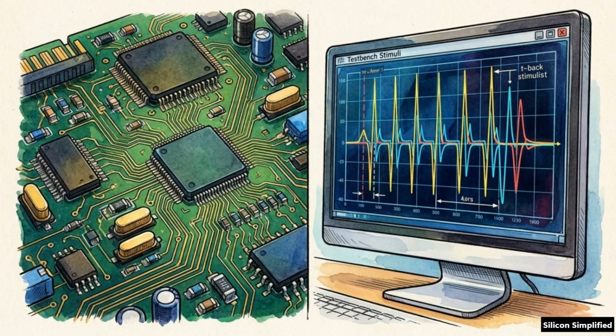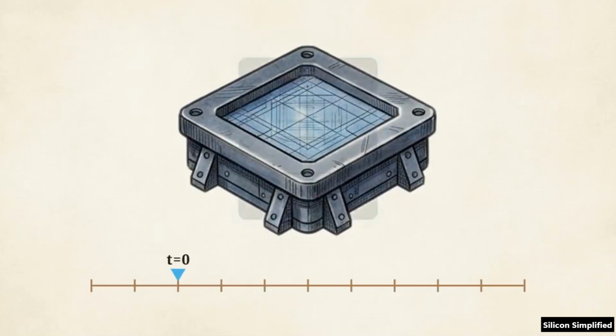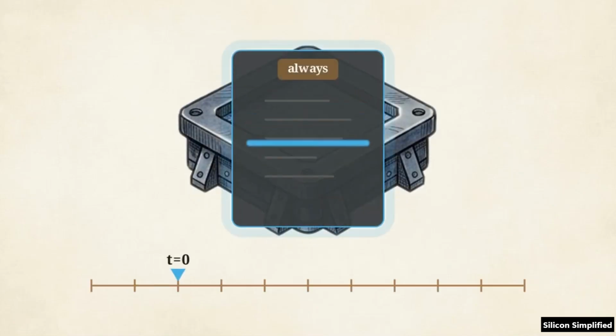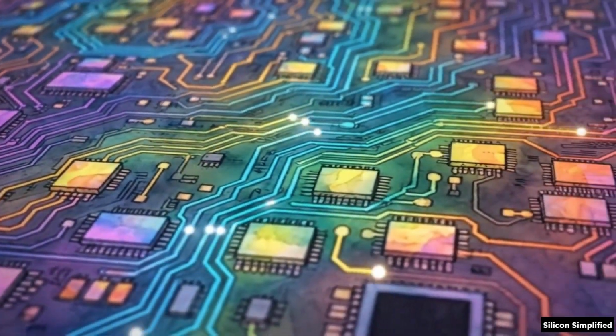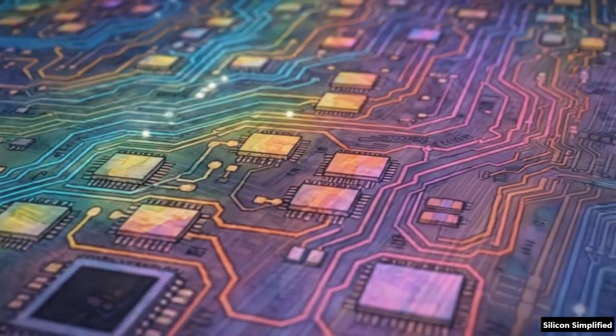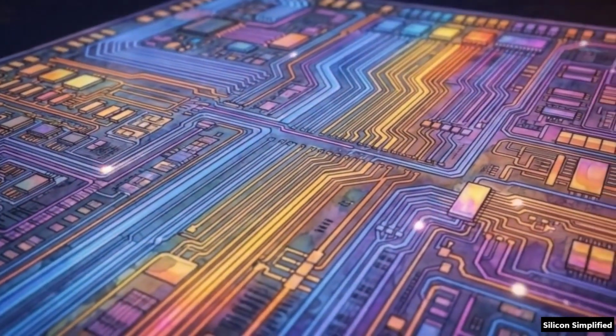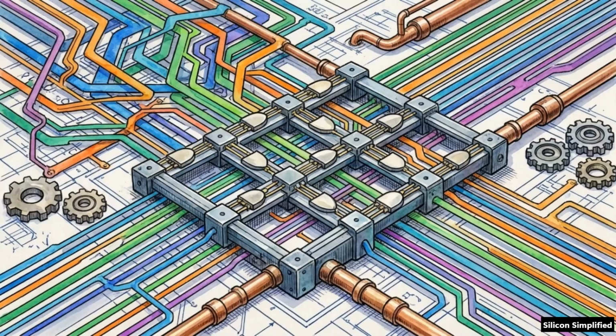Because physical hardware rarely runs a process just one time, initial blocks are exclusively used in test benches to generate stimulus waveforms. The second type is the always block. When an always block reaches the end of its code, it immediately reschedules itself and starts over, executing continuously for the entire life of the simulation. These blocks do not wait for one another at all. They operate as free-running, entirely independent processes evaluating in complete parallel. The baseline state of HDL simulation is massive, uncoordinated concurrency.